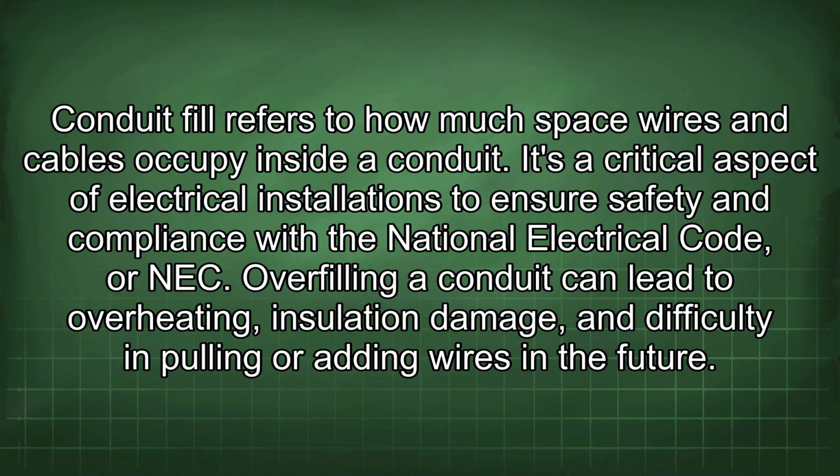Conduit fill refers to how much space wires and cables occupy inside a conduit. It's a critical aspect of electrical installations to ensure safety and compliance with the National Electrical Code, or NEC. Overfilling a conduit can lead to overheating, insulation damage, and difficulty in pulling or adding wires in the future.